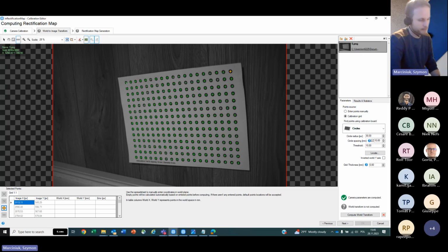That's especially important in applications with robots, because at this step I will specify a 0 point and axis direction for the real world unit coordinate system. And that's the same coordinate system that robots should be calibrated in.